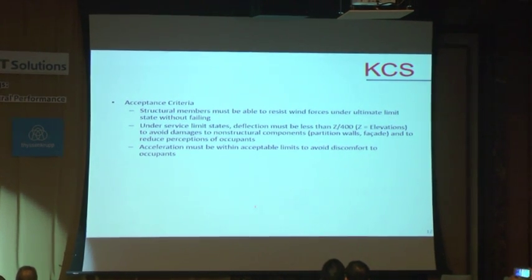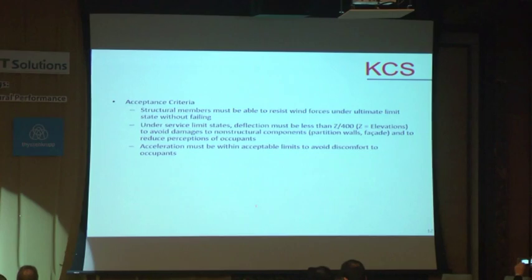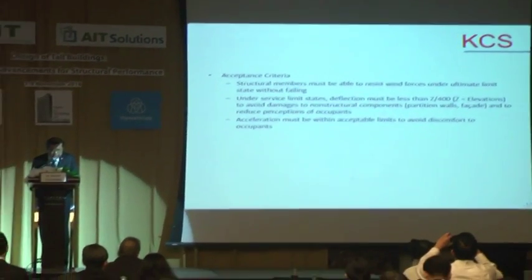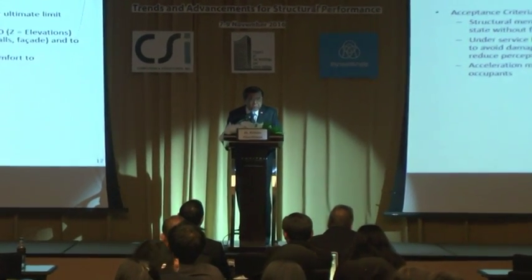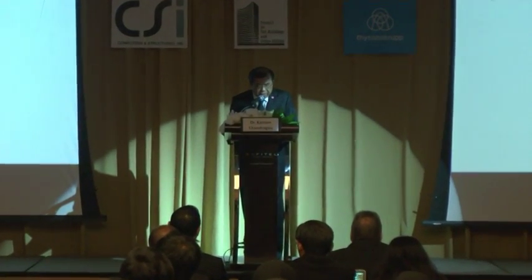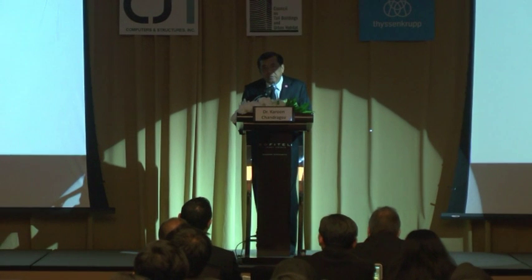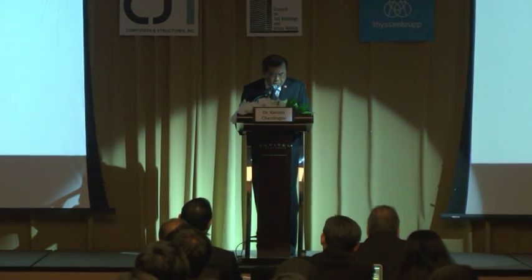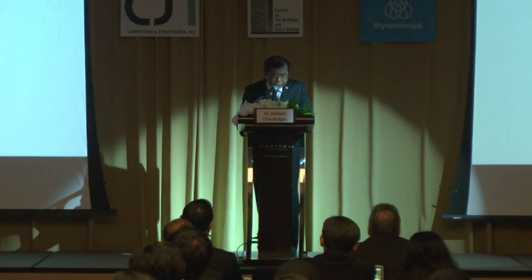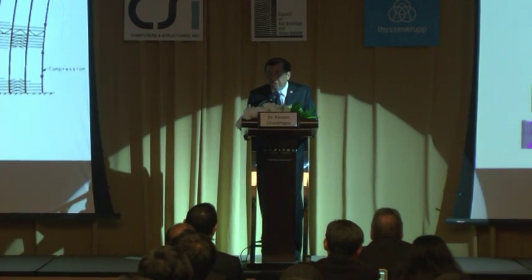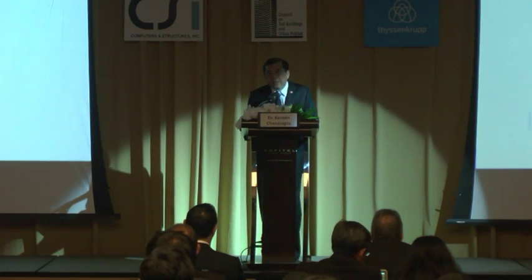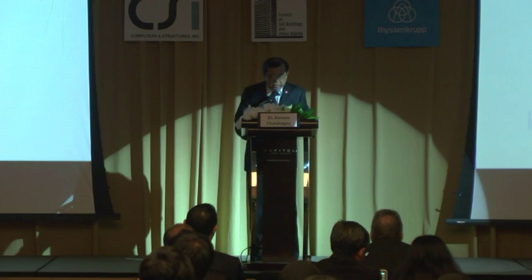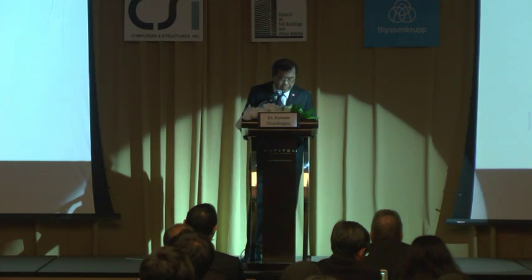To achieve those criteria, a special structural system consisting of wall-shaped columns and a large central lift core, together with outrigger beams, was used. With outriggers at two levels, we have managed to reduce the lateral sway to the limit. Therefore, a damping system was not needed.